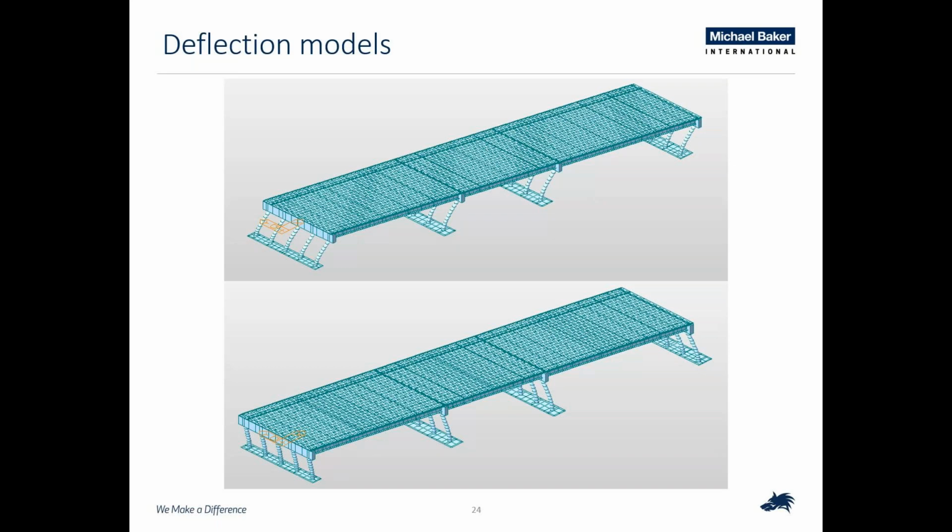So after that, the footings and piles were designed to resist the plastic overturning moments and those shear forces that we had gotten out of the general section designer. So we'd applied those just at the base of the columns on the footings, and analyzed those so that they would be able to resist the plastic overturning moments in the columns.